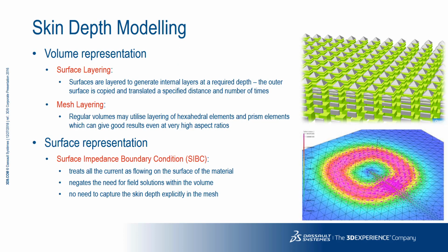Another practical consideration when performing FE analysis of eddy current NDT problems is skin depth modeling. It may be impractical, resource-wise, to mesh a whole problem with finite elements discretized to the size of the skin depth of the problem, so users need a way to accurately perform calculations at the surface, but utilize a coarser representation where the numerical integration points are unnecessary.